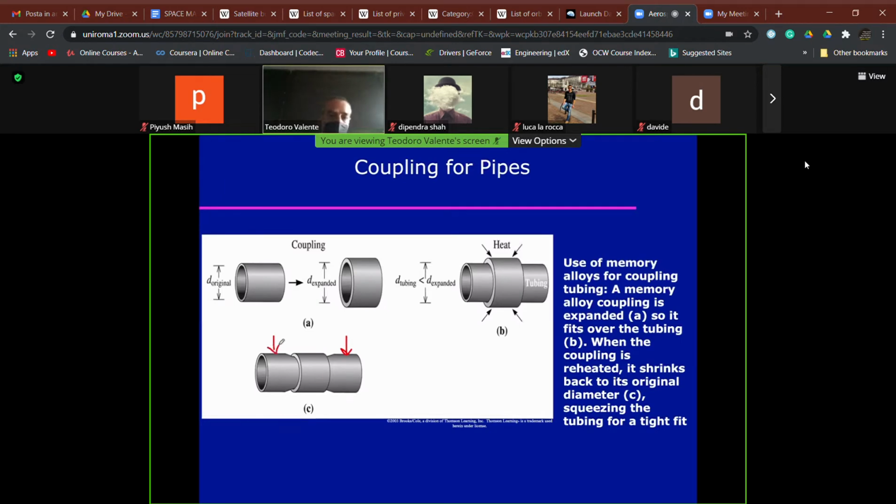One thing that we could think to do is to put a sort of ring, this one, which is able to fix the extremes of the two pipes. Obviously, in order to have an effective joint like this one, this ring that we insert must compress a bit the surfaces of the two extremes of the pipes. Otherwise, it will move along the length of both the pipes.